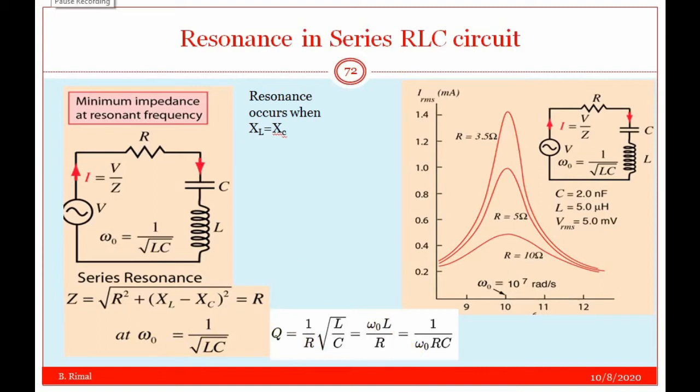Actually, the quality factor relates the maximum or peak energy stored in the circuit to the energy dissipated in resistance during each cycle of oscillation. That is, it is the ratio of resonant frequency and bandwidth. Here we will use this expression, which can be derived easily, in our series resonance transformer.